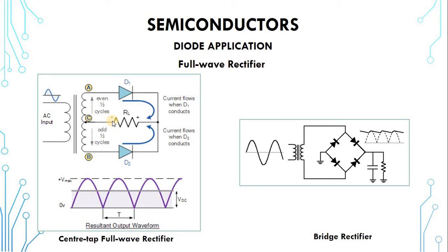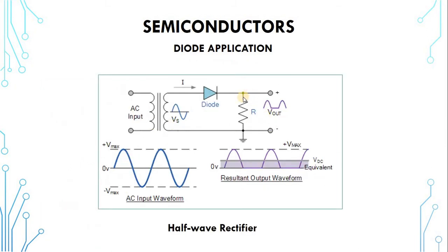So how does this help? Since we know that the center tap, C, which is a reference, is always negative, we connect the negative of the load to C, so that we know the negative is always seen there. Now we'll see how to direct all the positive to the positive terminal of the load. This load is supposed to be a DC load, which means that it does not like an alternating current, but it wants a direct one. In other words, this load always wants to see positive here and negative here. If you ever interchange it, it will spoil the load, damage it, or it will malfunction.